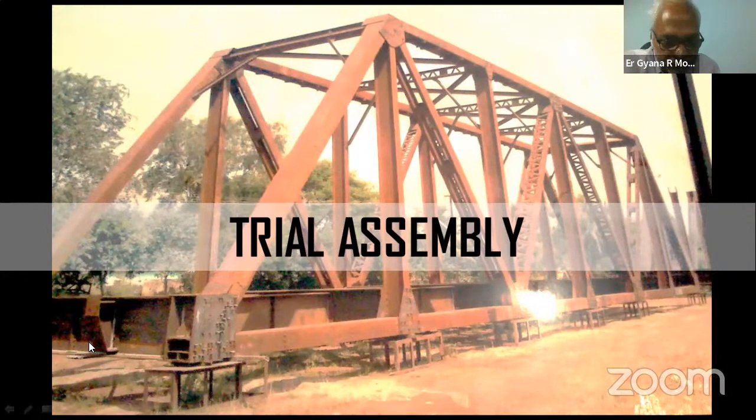So what is done is you first assemble the entire bottom level. You bolt the entire bottom level and put camber jacks at every node point. Then the other components are fitted. When you put the top chord, these holes will not match. What we have to do is keep the pressure here and forcibly match these holes, because these are shortened components. These have to be given a lot of force to distort a little and fit into it.